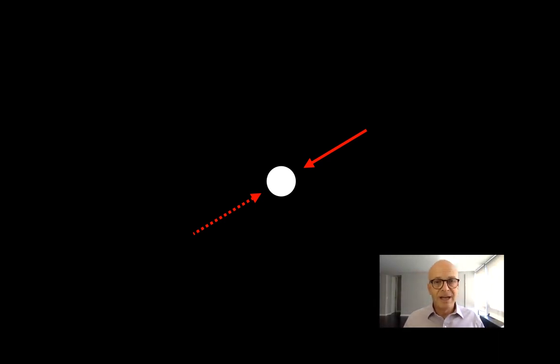And the goal in statics always is to make sure that whatever the loads are, we sum up all the loads, we put them on the free body, we figure out what the total of those are, and then we figure out what the equal and opposite force would be. And that's the reaction. That's what we'll be asking the structure basically to provide.